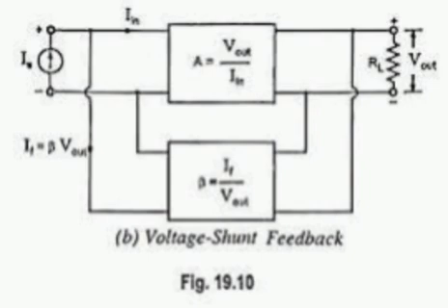Common gate amplifier. Unloaded voltage gain AV equals GM RD. Input impedance Zin equals 1 by GM parallel with RS. Output impedance Z0 equals capital RD. DC on state resistance RDS on equals VDS by ID, where RDS on equals DC resistance in the saturation region, VDS means DC drain source voltage, and ID means DC drain current.